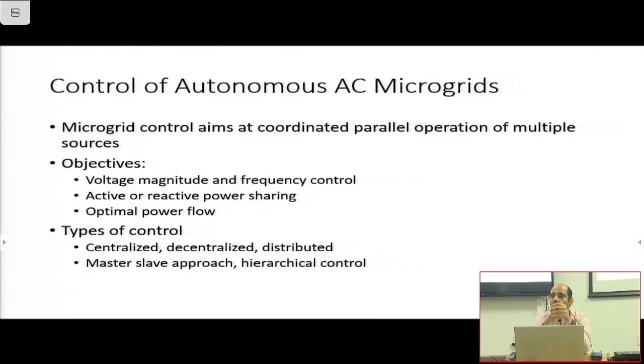But then suppose there are 4, 5, 6 inverters, multiple inverters, and each one of them is working at their own frequency. Okay, well and good, but the problem is, in an AC system, proper synchronization is not just the frequency but the phase angle as well. Yes. So one is the synchronization issue out there.